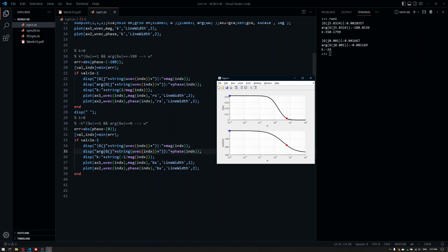Again, I repeat, these two conditions, one given in line 18 with 17, and 29 and 30, are important to note because those are basically summarizing it. We're looking for the point where the phase of the system is -180 degrees. Take that frequency, plug in that frequency, get the gain or magnitude value, take the inverse, and you end up with the positive bound.